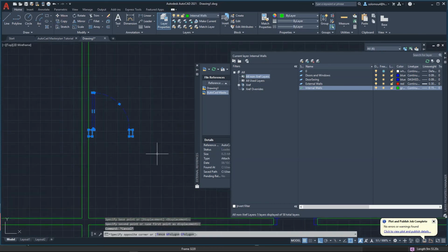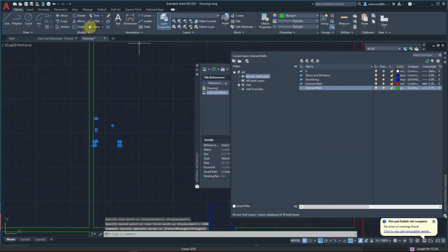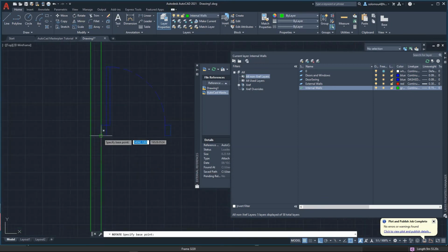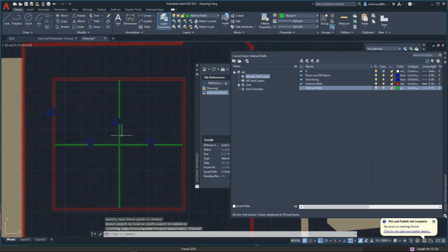If you want to be extremely accurate, which is how you should draw buildings, you go down to this point there where the wall starts and say I want it to be 3 meters from that wall opening. So we write, okay, 3 meters. We press enter. There we go. And now from that point onwards, if we rotate it again from here, we're going to rotate it up to there, now 90 degrees. There we go. Perfect. And we just select these two things and trim between them, these two lines. There we go. See? Now that is 3 meters from the edge here and opens up.